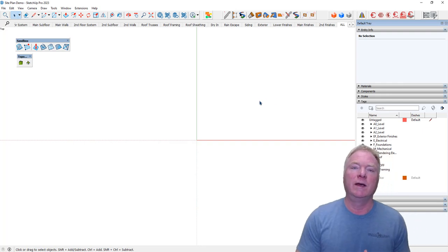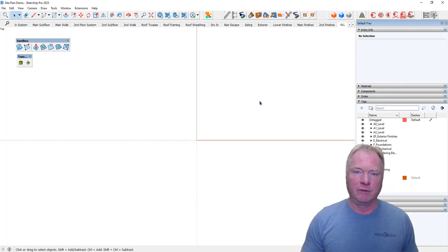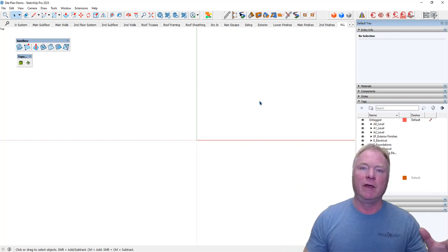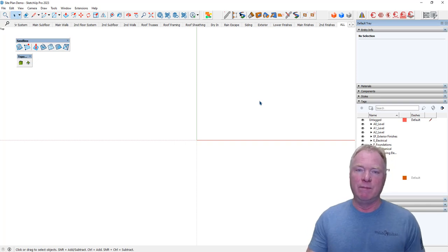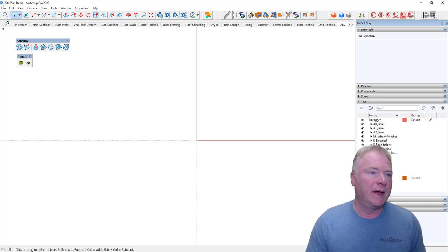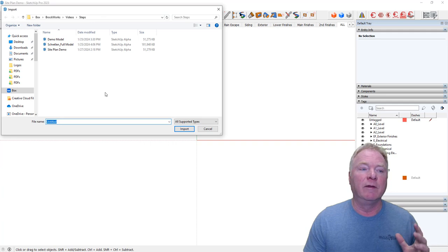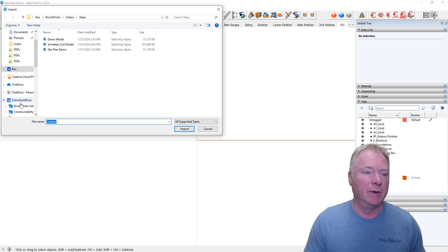So the first thing I do is set up my project. We take our sites and we rotate them to fit the house, not the other way around. So I want to start out with bringing in the plans that we're going to be building off of. The first step for us is using PDF Importer. Disclaimer, that is one of our extensions, but we need to bring in the floor plans that allow us to then build on top of them.